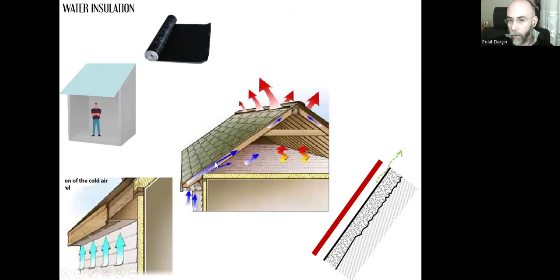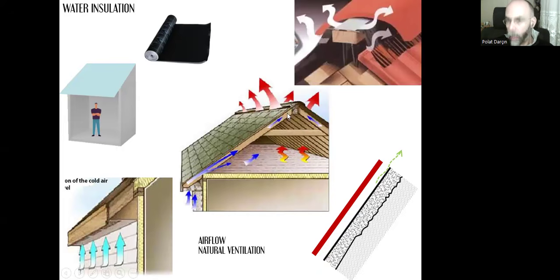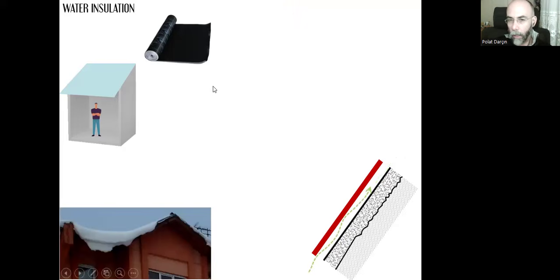And through this channel, we can circulate the air and sweep away the excessive gas. And at the ridge level, again, we can create tiny little gaps which won't let water come inside, but let the air pass through easily using these types of plastic substances. It has these tiny air gaps positioned in this line here.